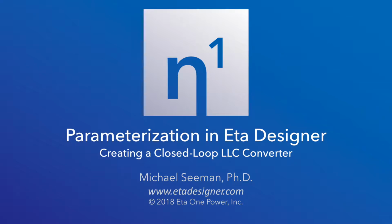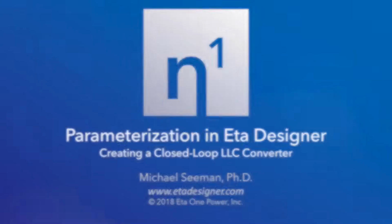In this video, I'll use parameterization in Eta Designer to create a closed-loop 600-watt LLC converter. I'll use design variables to select component values and then understand the waveform timings and home in on the right converter parameters. Finally, I'll close the loop and use parameterization to quickly stabilize the converter and optimize the startup response.